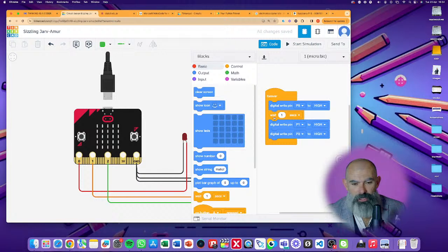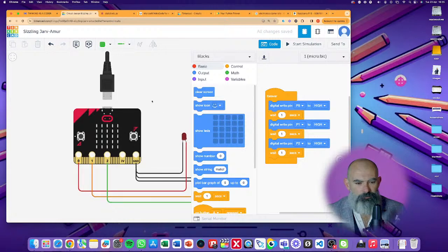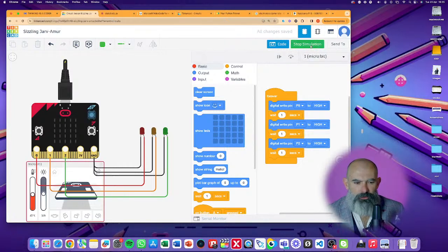So here we are. We've got our wait 1 second, and I'm going to drag those in a little bit, so I'm going to wait 1 second between each point. When I press play now, and I move this off to the side, see if you can guess what might happen. Digital in, wait, digital in. Have a look. Hopefully you thought that this was on. It was like a sequence. But I didn't want that to happen. That would be a crash if that was an actual traffic light.